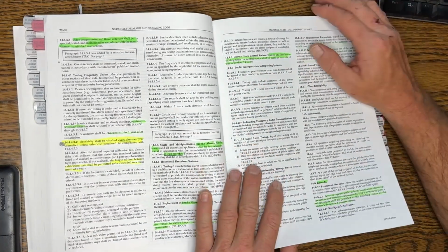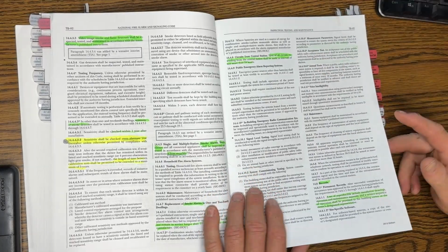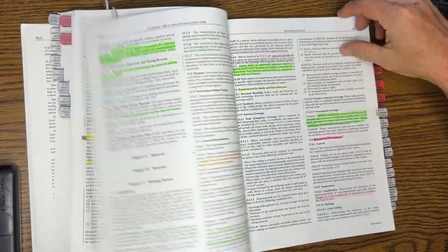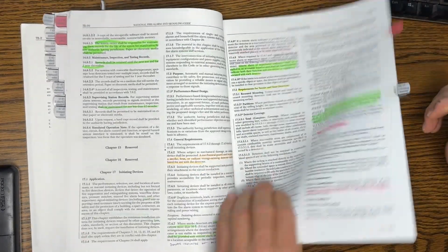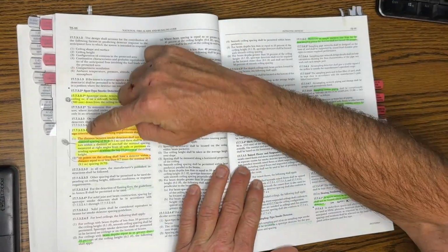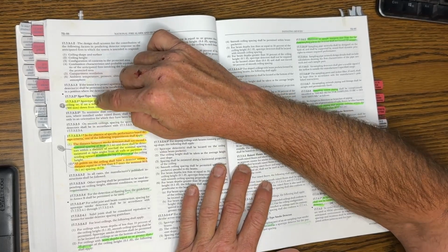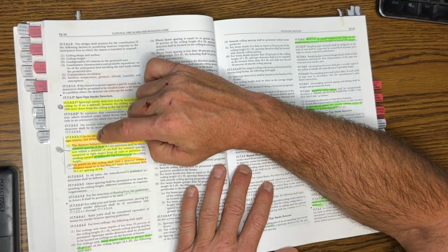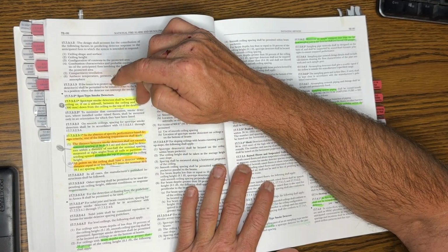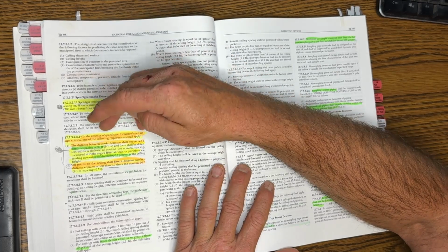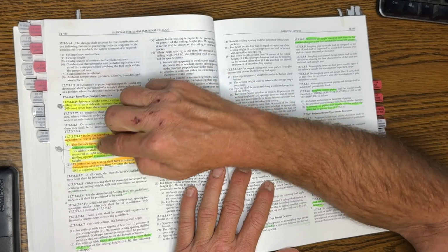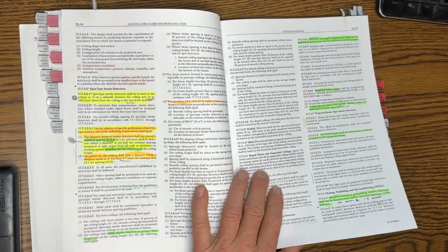Let's see. So next one, I'm not going to read every one, but it's 177321. Let's use these tabs up here. 177321. There you go. So right here, and then the next one was 3231 here. So highlight these two. Spot type, smoke detectors, how far from the ceiling to the top of the detector is 12 inches. In the absence of specific performance-based criteria, one of the following requirements shall apply. Just read through that.